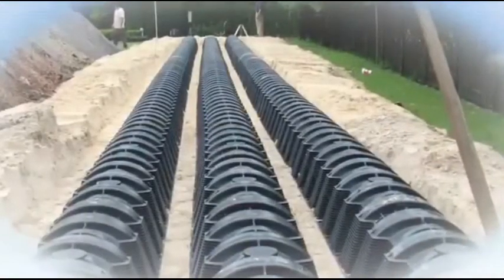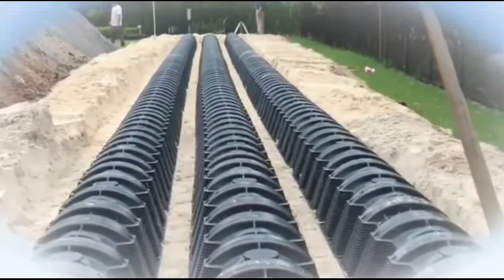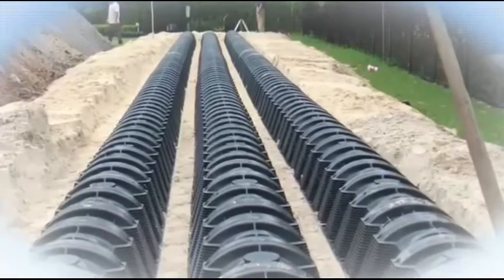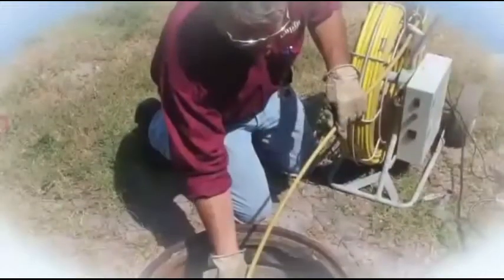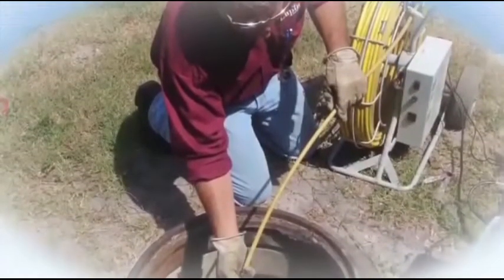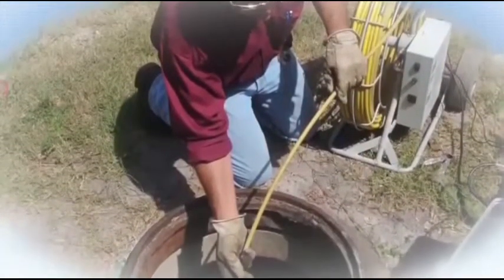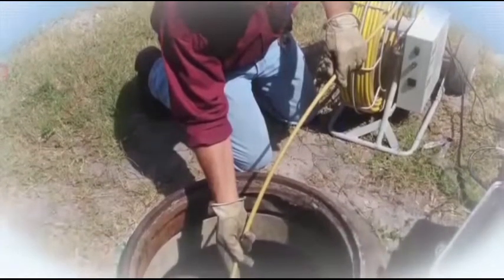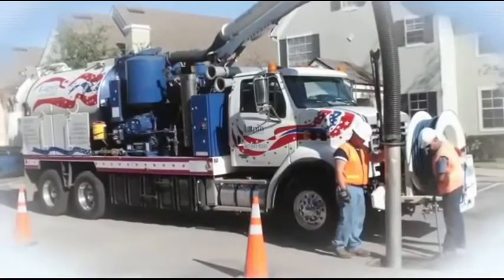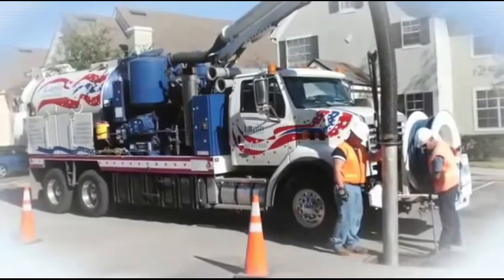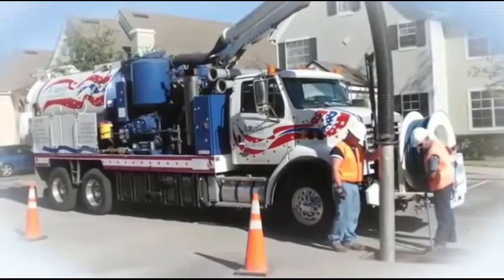This type of system consists of a series of connected chambers. The area around and above the chamber is filled with soil. Pipes carry wastewater from the septic tank to the chambers. In the chambers, the wastewater comes into contact with the soil. Microbes on or near the soil eat the influent.